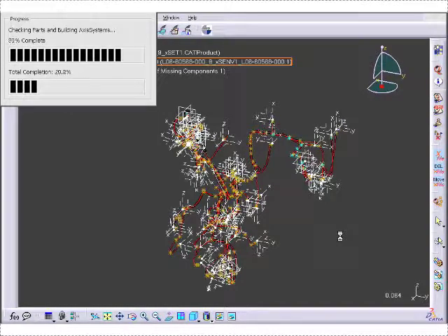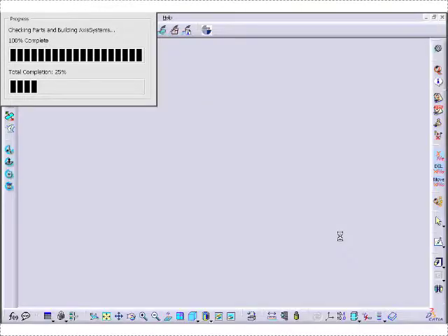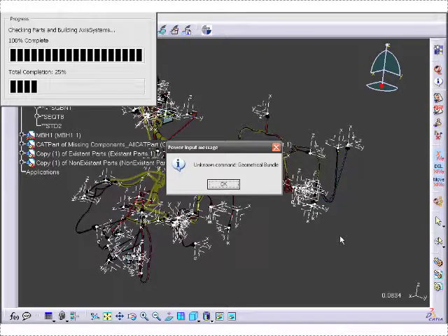But it goes several steps further in finding the actual parts that your company has cataloged. It brings them into place, and then it even connects them up with the V5 harness. Now, as we just sit here, this is real time. There is a little bit of delay in this macro. It has to go through, and if you could see in this conversion, there's hundreds of parts that it's kicking over, so it does take a little while.